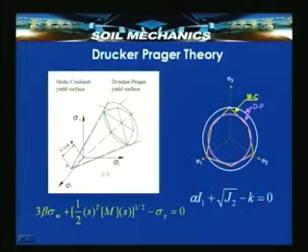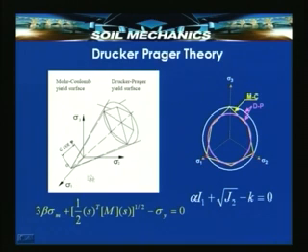If you look at this figure, for example, this is a 3-dimensional stress state figure, sigma 1, sigma 2, sigma 3 are shown as axes, and now suppose you plot all those points which correspond to failure as predicted by the Mohr-Coulomb theory, then what you will get will be in 3 dimensions a hexagon like this, a hexagonal hollow surface. That is what you will get. In 2 dimensions it looks as a straight line.